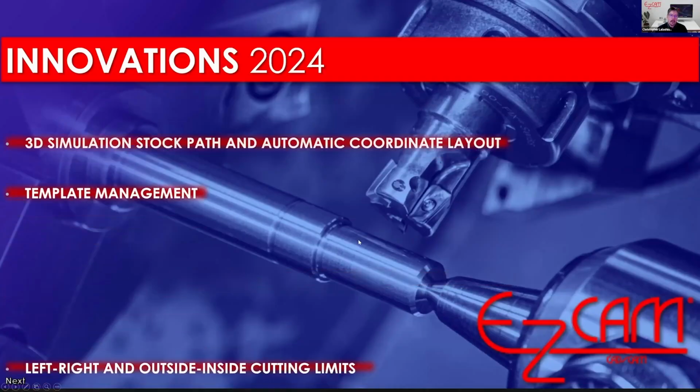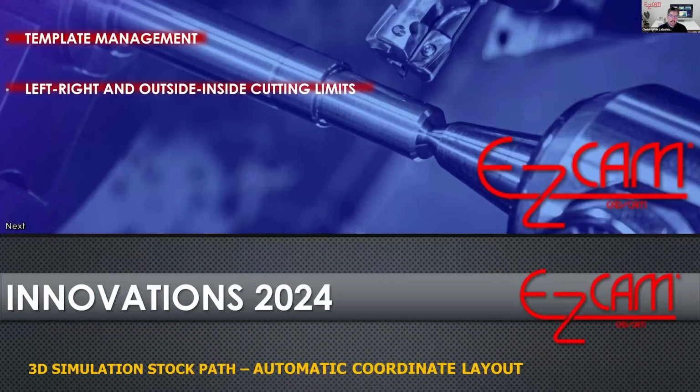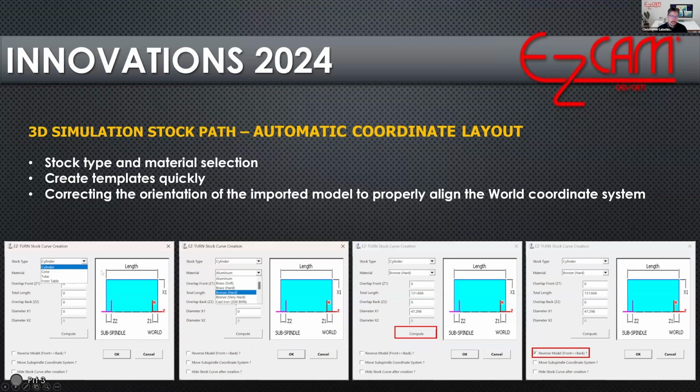Let's talk about the stock, template management, and our boundaries. Over on the left-hand side, you can see that we're selecting our stock type. Then over here on the next slide, we have our different materials for the part. This will load the corresponding templates because the template needs to be different when you're cutting aluminum or cutting bronze. Then we have compute, where we'll give you the length of the part and the diameter. And lastly, you can reverse the model if it comes in backwards.